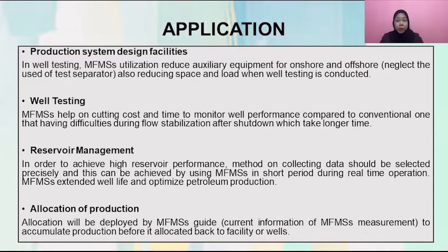Okay, the third point is reservoir management. MFM can provide real-time continuous data to enable operators to characterize field and reservoir performance better and react faster. For example, changes in gas or oil ratio or water cut can be detected and quantified immediately, whereas a traditional test separator provides information only about cumulative volume at discrete points in time.